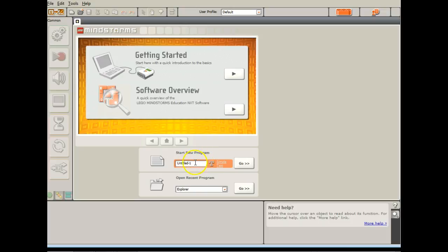or by default it comes up and gives you one. Default in computers means what your computer uses if you don't tell it differently. So normally computers have defaults built into them. That way you don't have a lot of syntax errors. It'll stick something in there until you go back and do what? Change it. So over there on these robots, if I tell it to do a move, it's automatically going to give me a speed, and it's going to give me a round off, an accuracy of the point, because that's required by the instruction. So when you stick it in there, it's going to do that for you. And then what you would do is you would go back and change it.